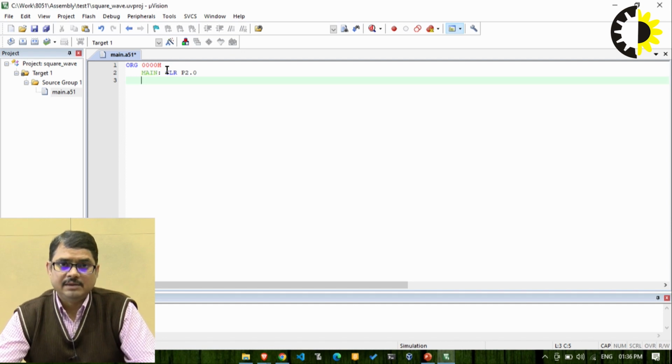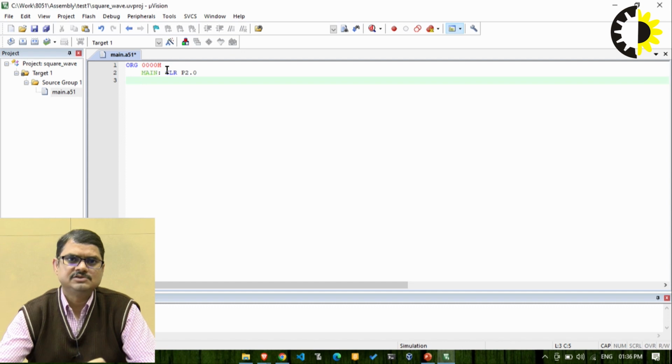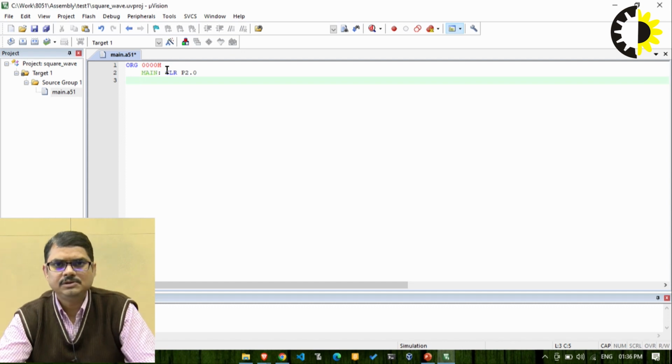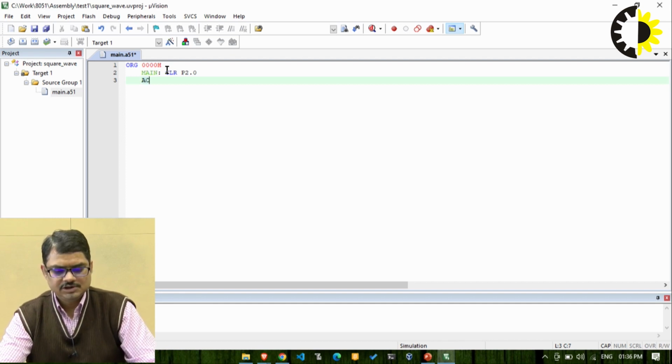This is called a time delay operation. To generate a delay, we can use the concept of a subroutine. Subroutines are basically special programs which may be called in your main program whenever needed. To call the subroutine, I am using the call instruction, that is ACALL, absolute call.